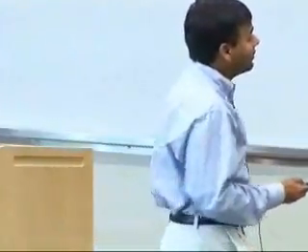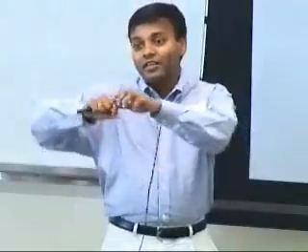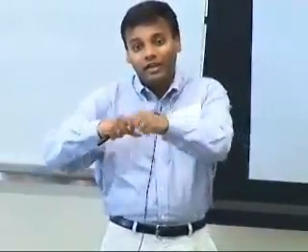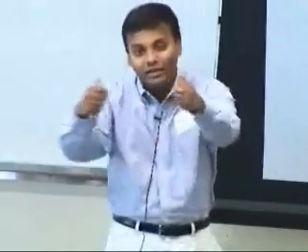And what was found is that BISER was very effective in correcting single event multiple upsets. The reason is, first of all, because of the diversity that I was talking about, and also BISER doesn't have any self-regenerative feedback. It's not like, if you have an error, you make up for it and you feed the same thing back into the flip-flop. It's a feed-forward kind of design.